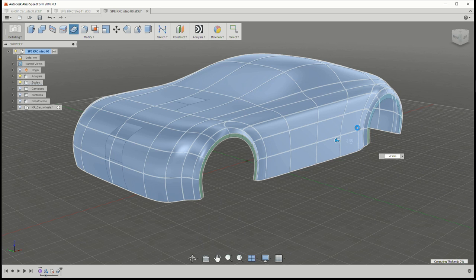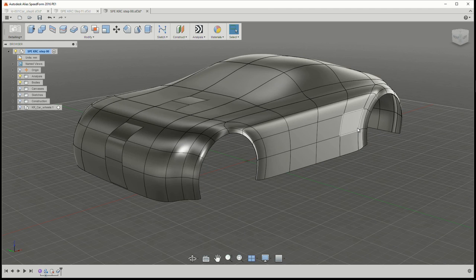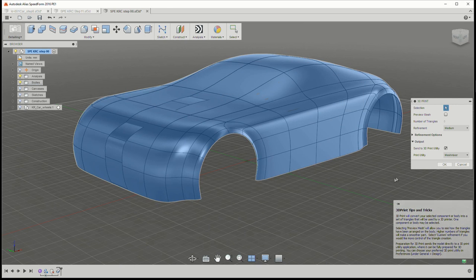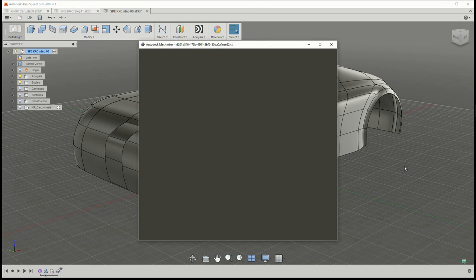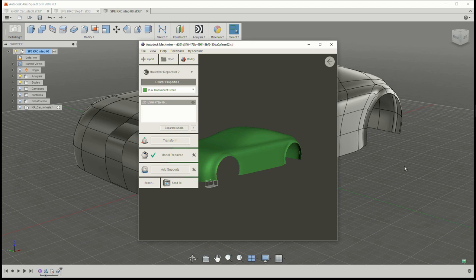Was it possible to convert this SpeedForm shape to mesh and take it to Alias and use the surface from mesh and make it better or simpler or bigger patches? Yeah, so the question is is it possible to convert this into a mesh and then move it into the same process? And the answer is yes. The next step of this, for example, would be I might want to do a 3D print of this particular file. So I'll grab this and tell it to create a mesh. So it's a solid. I've got a thickened surface structure, and it's going to do the necessary operations to create an STL file of that. And I could have adjusted what that is and then save the STL file and pull that in. There's an OBJ output from SpeedForm, so I can output in the OBJ, so just the surfaces from there. So your choice as to how you would like to do that. So here's the ability to do a 3D print of this.